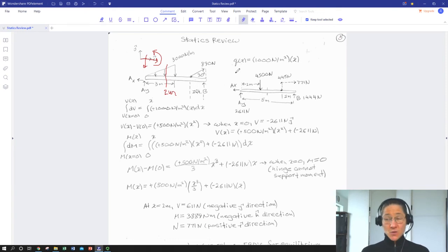But just to step through what we've already learned about this from statics, as in almost every case, we would solve for the support reactions. So that's this FBD over here, where we've taken our distributed load and done a quick shortcut, taking 1/2 base times height to get a magnitude.